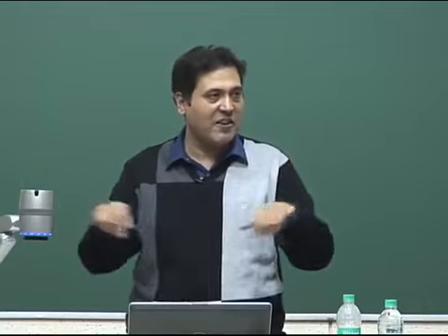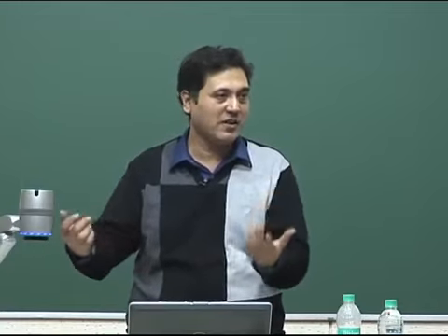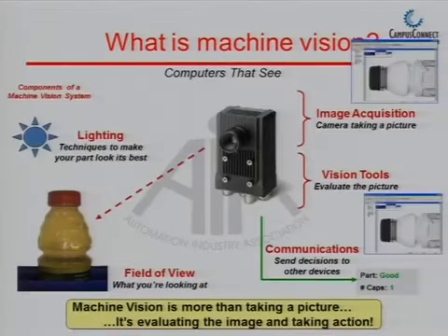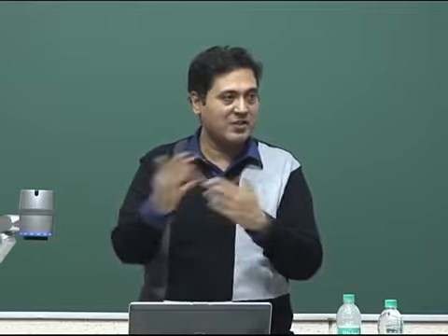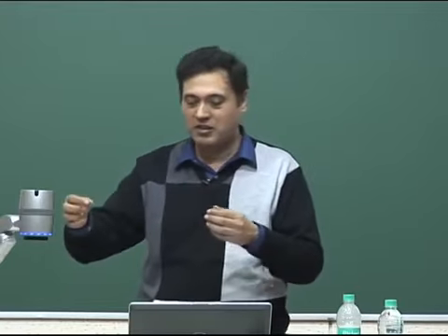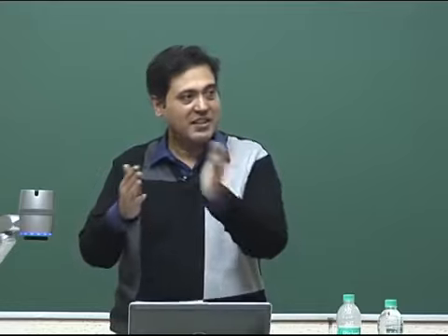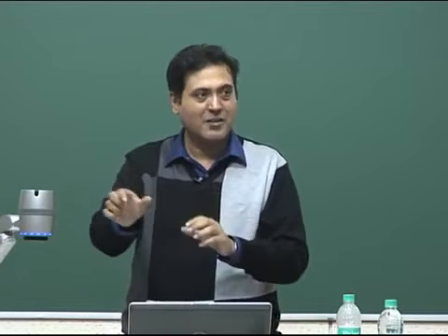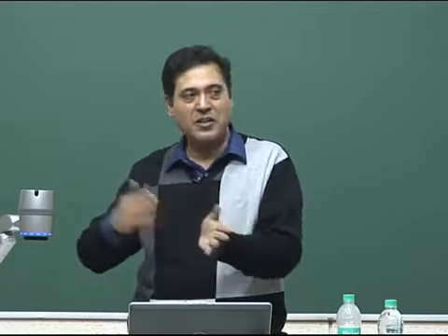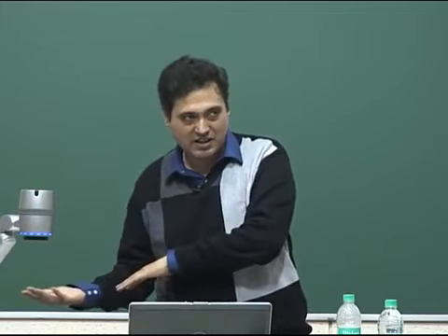Within that field of view, you have to adjust the focal length so that the images do not blur out. It gives you a crisp picture of the component, and those images are then taken to the software, and there are different tools for doing it. There is a common tool known as a pattern tool, which does 1:1 matching of the pattern. Then there is an edge tool, which compares the contrast value to detect the presence. So, these are different tools which are totally dependent on the software of the camera.